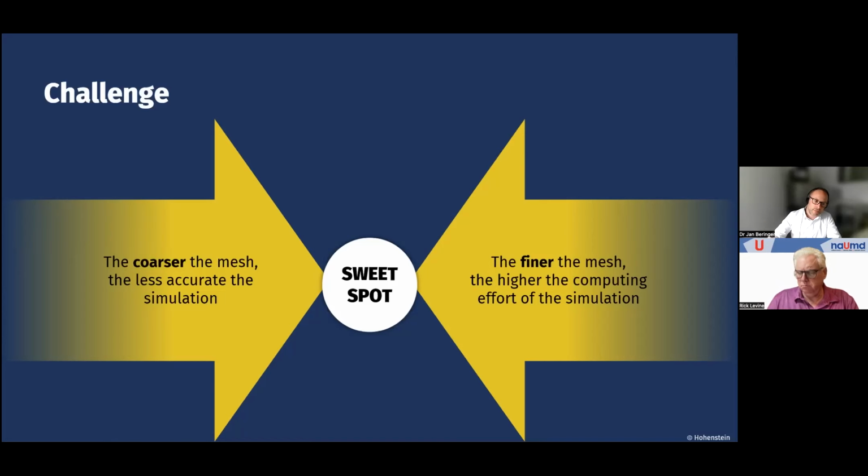So finding the sweet spot, and let's say getting some information a little bit earlier up front, you have the information later in the summary. It depends on the application that you actually use 3D simulation for. Is it just design approval? Then you can do it a little bit faster. If you're really going into details, for web shops, for example, you have to increase the mesh resolution, but I will come to that later on.